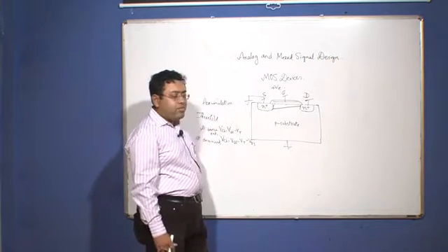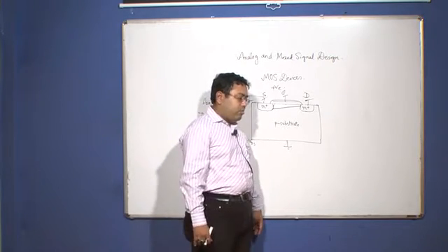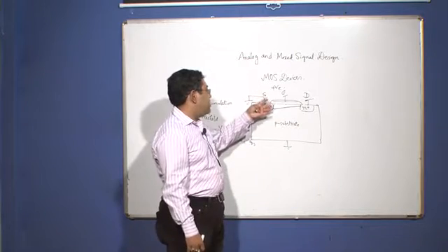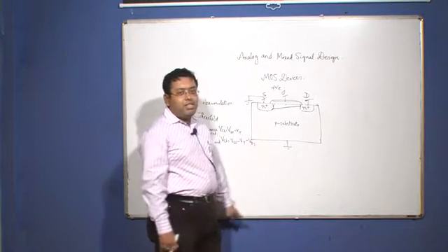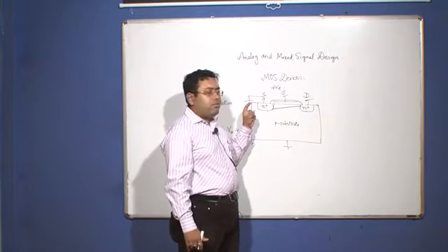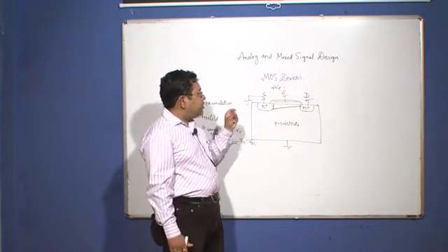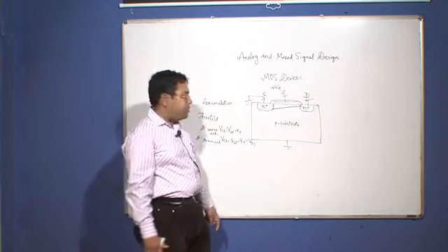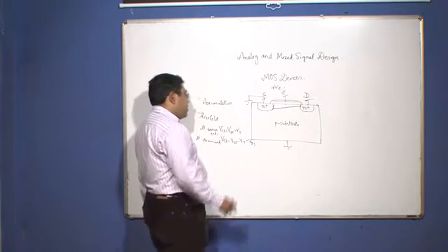So if you take a transverse section across the MOS device, you will find that it basically takes the shape of a trapezium, being broader at the source end and gradually narrowing down as you approach towards the drain.